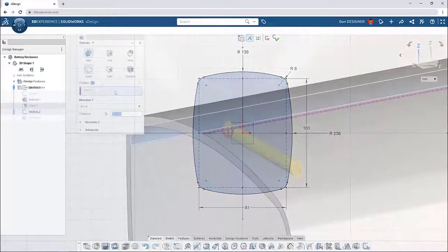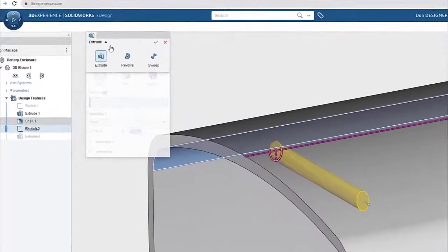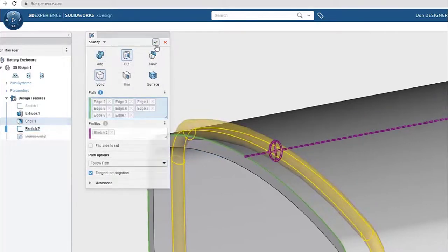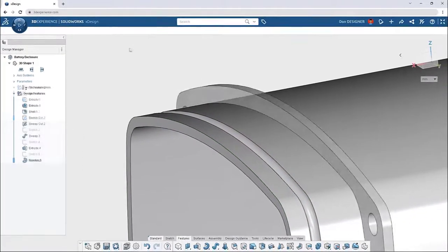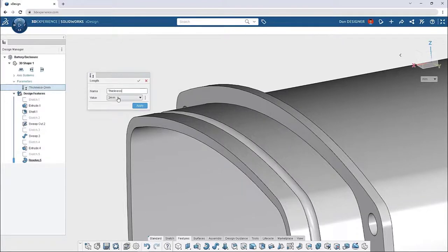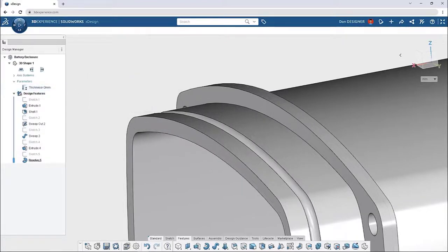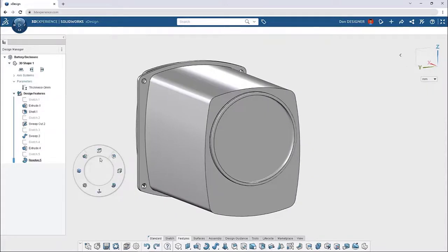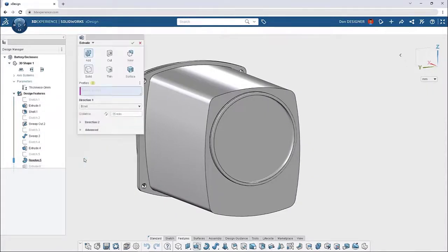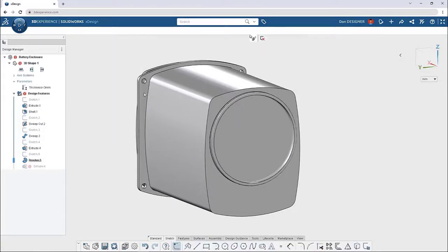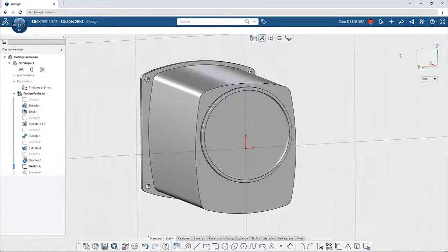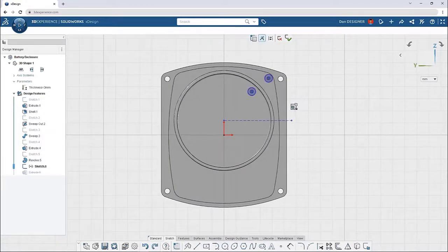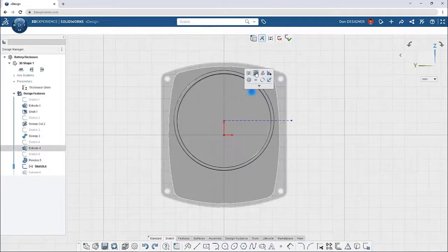Switch between extrude, revolve, and sweep, all from one command with super features. User parameters can drive both sketch and feature geometry, so design changes update predictably. Shortcut rings adapt to the working environment to keep the most relevant commands close at hand, and command parking adds sketches or reference geometry on the fly without leaving the feature.